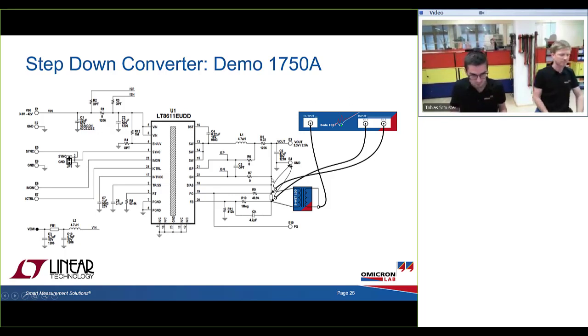Setup is always channel 1 and channel 2, and the ground connected to common ground. For the injection resistor we normally use 5 to 10 ohms, but afterwards in the presentation, where we discuss how big the injection signal should be, there are further details on the injection resistor.